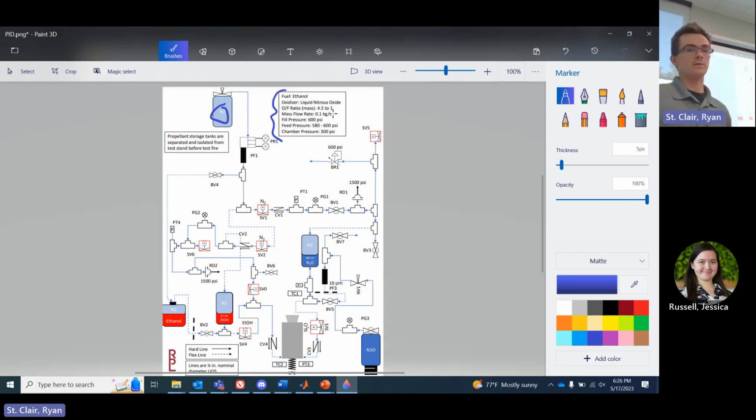So for example, alcohol with nitrous oxide has a stoichiometric ratio of 5-to-1, 5 units of mass of oxidizer to 1 unit of mass of fuel. We're just below that with 4.5 because we are only planning to fire our rocket engine for about 4 seconds. If you're designing a different engine, you can go for different OF ratios, and this is highly a factor of the pressure behind it and the geometry of the injector. So how much are you restricting the flow of the fuel to get more oxidizer out instead of fuel?